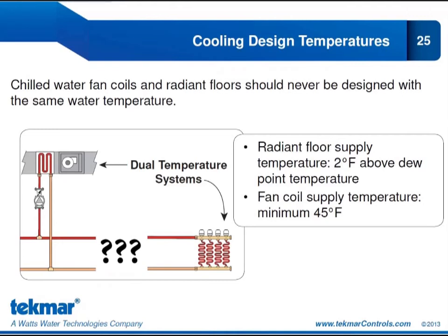This is definitely a dual temperature system where we have different needs for supply water temperatures going to the radiant system as we do to the forced air system. Without two water temperatures, it's impossible to have a well-controlled cooling system. The dew point reset temperature will make the water temperature for the fan coils too high, and thus very unlikely to satisfy the cooling loads and dehumidification set points.